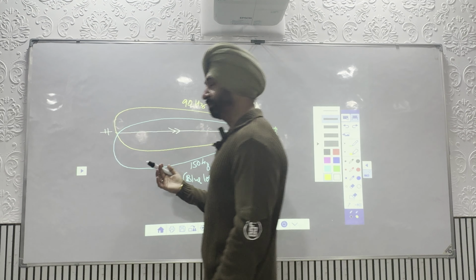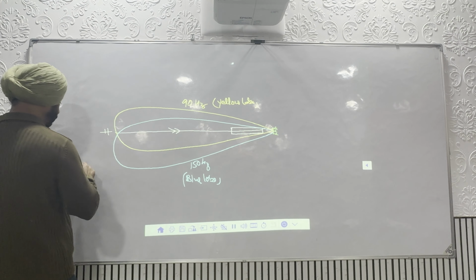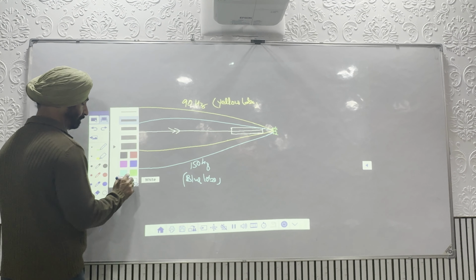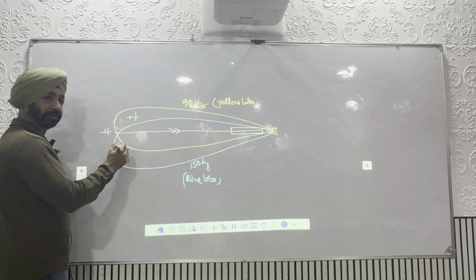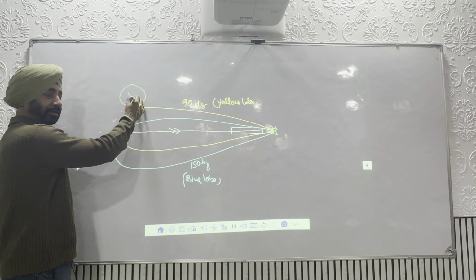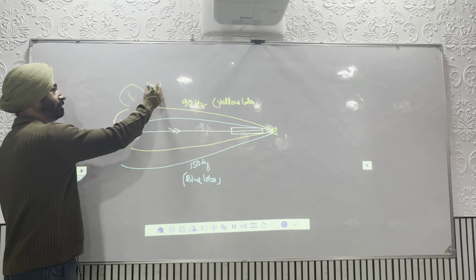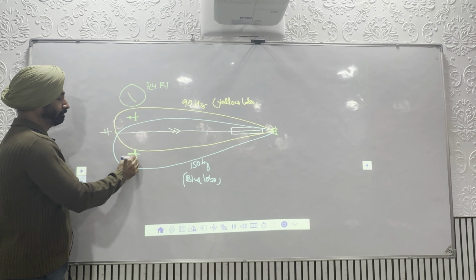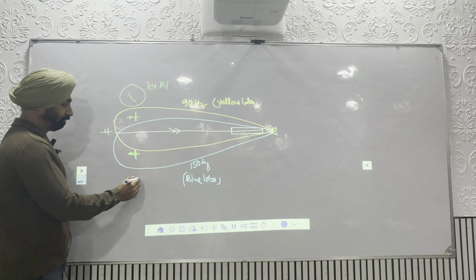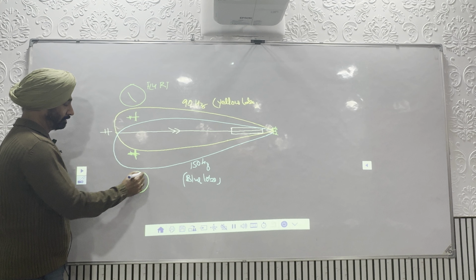There is no confusion. So if I am on the left of the approach, I will receive more of 90 hertz. It will give you a fly right indication. If you are here, which signal will you receive more? It will tell you a fly left indication.